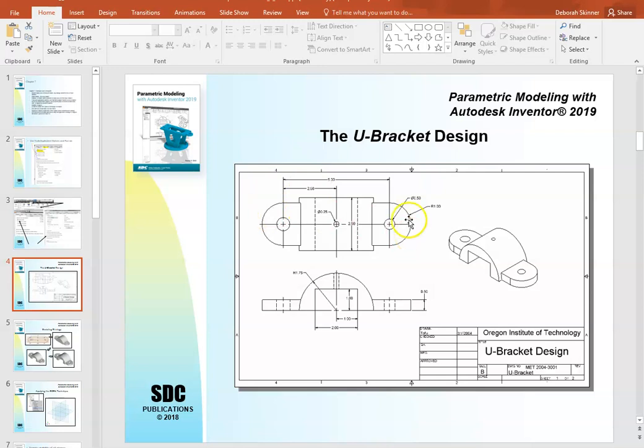Now, I mentioned the other day if you've got a circular pattern, even a half circle that's shown, sometimes that's a good place to start. So this one's got a half circle in the front view and then it's got circles in the top view too. Since the half circle in the top view is extruded differently in regards to length, it's not level with the edges of the other circular pattern.